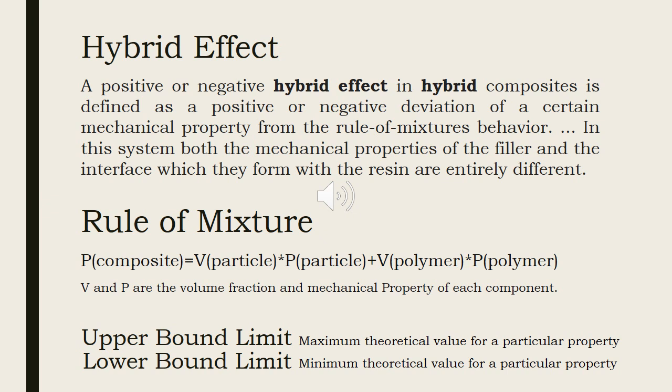Hybrid composites have greater possible control of specific properties, achieving a more favorable balance between the advantages and disadvantages inherent in any composite material. Thus, for example, by combining two types of fillers, a reduction in modulus will bring increased fracture resistance and reduced cost for the composite.